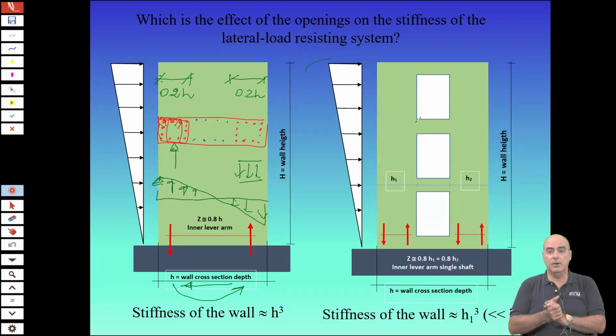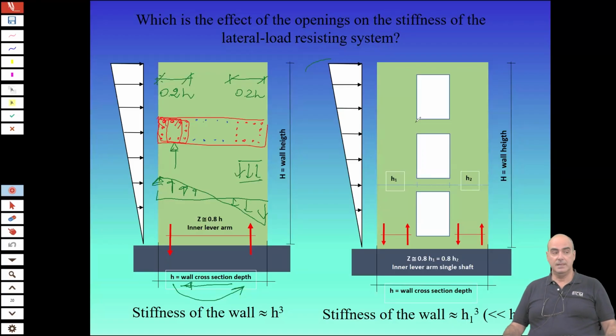And if you have a door, which is generally the minimum opening you have. Well, consider that this is not a door inside an apartment. Those doors are 90 centimeters typically. This is a door, the main door for offices or for an apartment building, the entrance door. How wide is that? Do you have an idea? Yeah. For example, in hospitals you have wider, but the minimum is 1.2 meters.